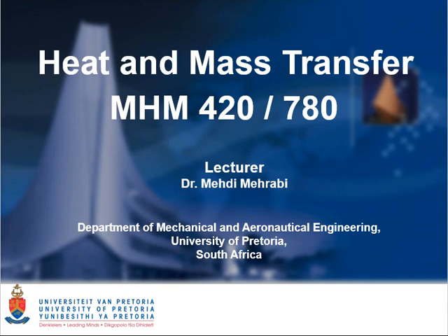When you are dealing with the first situation, it means that you need to select a heat exchanger to satisfy a specified temperature change. You need to use the log mean temperature difference method. And why? Because you have all those temperatures.